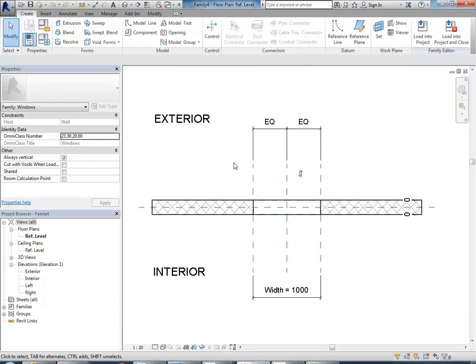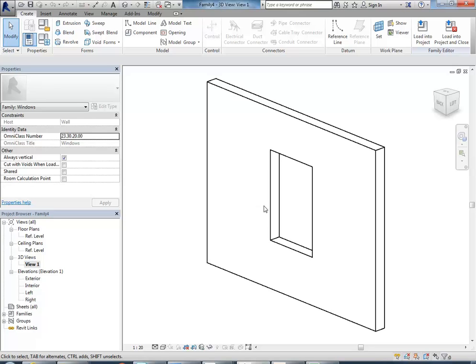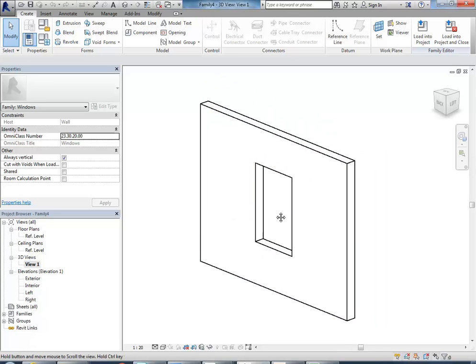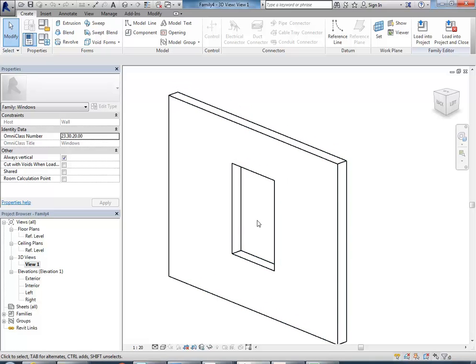And you'll see that gives you a wall with an opening already set up. So the wall won't come in when you load your window in, only what you put into that opening. So into the 3D view there, I can see the opening, and so a good approach there is to set the size. If you know you have a certain size to work with, set that before you start modelling. And so remember, to get to your properties, you've got that Family Types button.